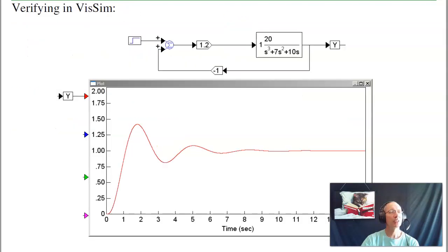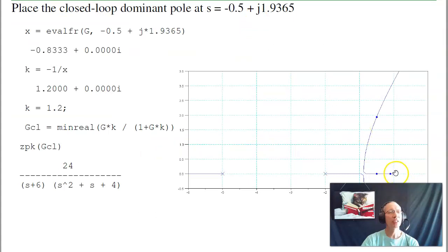So what I do is on this root locus plot, I go up, turns out to be 63 degrees, go up at that angle until I hit the root locus plot. At that point, that's my design spot. At any point in the root locus, G times K is minus 1. Evaluate G of S at this point. Pick k to make the gain 1 there.